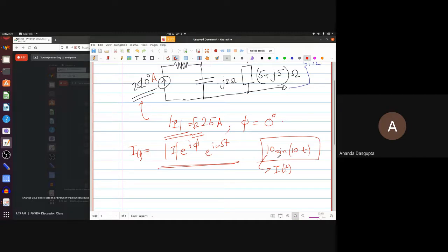At the same time, you don't have to worry about it, because when you say the current is this much, you're also quoting the RMS value. When your answer says the current is something, you are not giving the actual time dependent form with the amplitude and the phase and everything. You are giving it in this notation, the same notation as this one. So ultimately, this factor of root 2 is there in every one of the voltages, in all the currents and so on. Whether you include the root 2 or not in your calculation, you will get the same result.